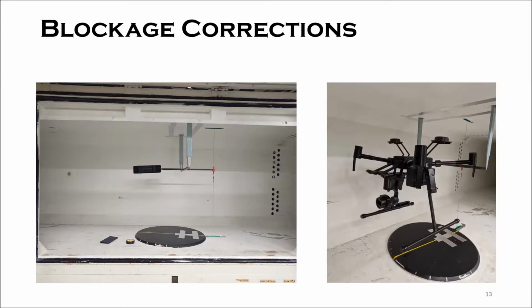By comparing configuration 1, represented by the main body, and configuration 9, which is the full assembly, we can see that the presence of a body as well as the size of the body will surely have an effect on the airflow. Referring again to the continuity equation, the reduction of area leads to the increase of velocity and dynamic pressure downstream of the model.